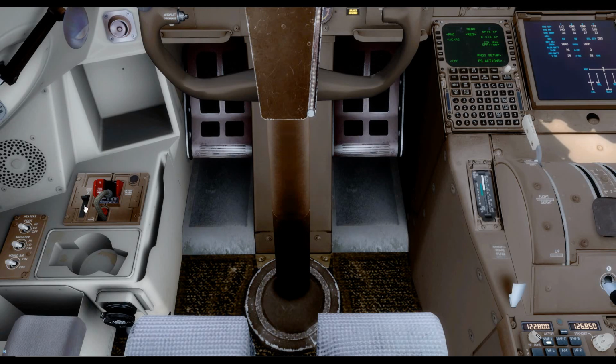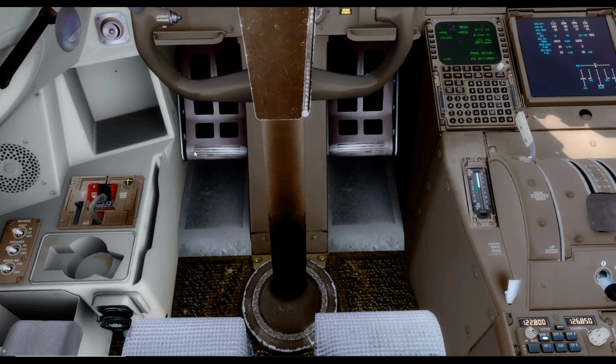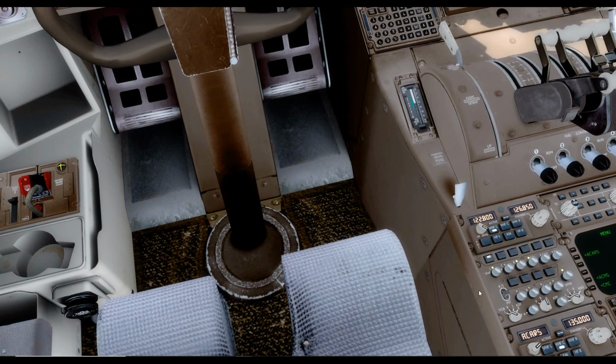We're then going to depress it again in conjunction with the emergency test selector. You can see a continuous flow is shown in the yellow cross, and you can hear the continuous flow as well. We're also going to use the intercom switch here, and you can hear the flow on the overhead speaker.